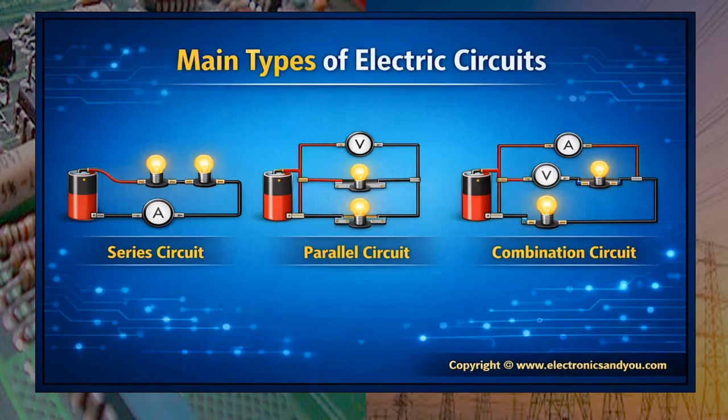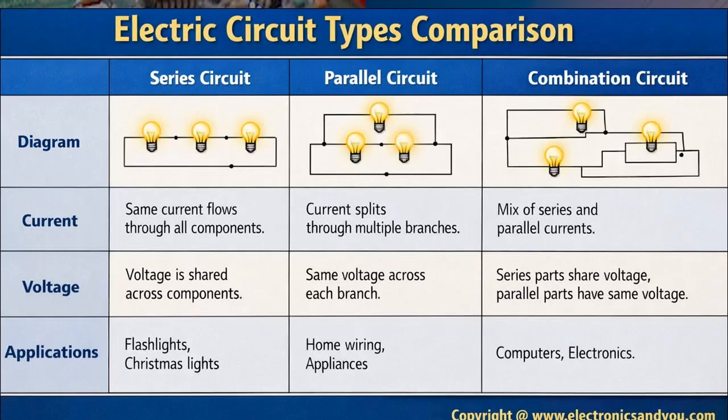Combination circuit, when you have a series parallel arrangement, we do have complex circuit when series and parallel circuits are put together, but the same principle applies. If you want to measure voltage, connect the voltmeter in parallel with the load. If you want to measure current, connect it in series with the load to measure the current across that.